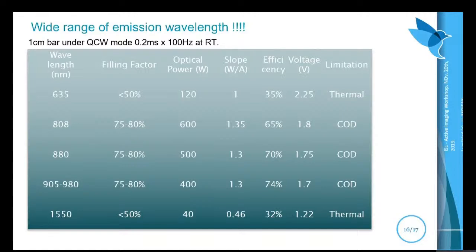products. We have to take into account some limitations in operation. Maximum optical power can be limited in certain circumstances and, depending on the wavelength, is limited by two factors: either the COD, catastrophic optical damage, in the near-infrared, or thermal effects in the visible or in the SWIR.